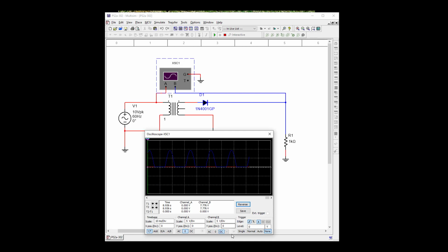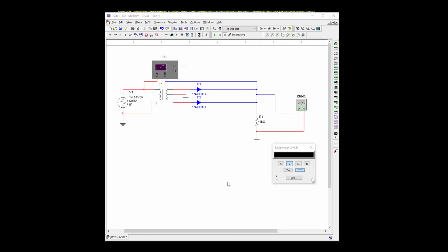And let's see here, if we go ahead and turn on our AC, that is our input. Okay, and you see the blue's a little bit smaller. Well, that's because of the 0.7 or 0.5 volt drop across our rectifier. So that's normal. So let's go ahead and block that. But that is a normal half wave signal.